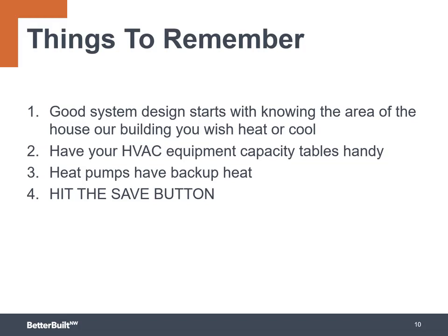And remember that when we're dealing with heat pumps, you don't have to have 100% heat at the design temperature. They will have some form of backup heat, so you want to make sure that they're sized to optimize the system performance and comfort, but not necessarily meet all worst case conditions. And of course, always remember to hit the save button between going from tab to tab.